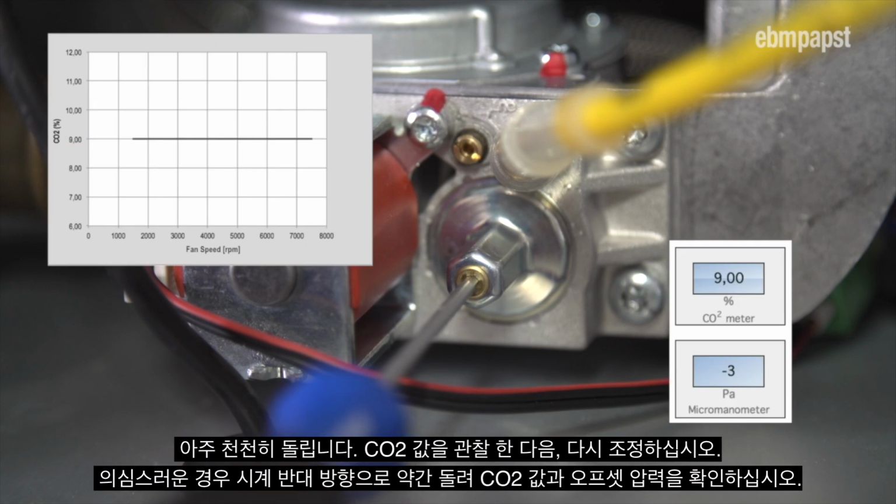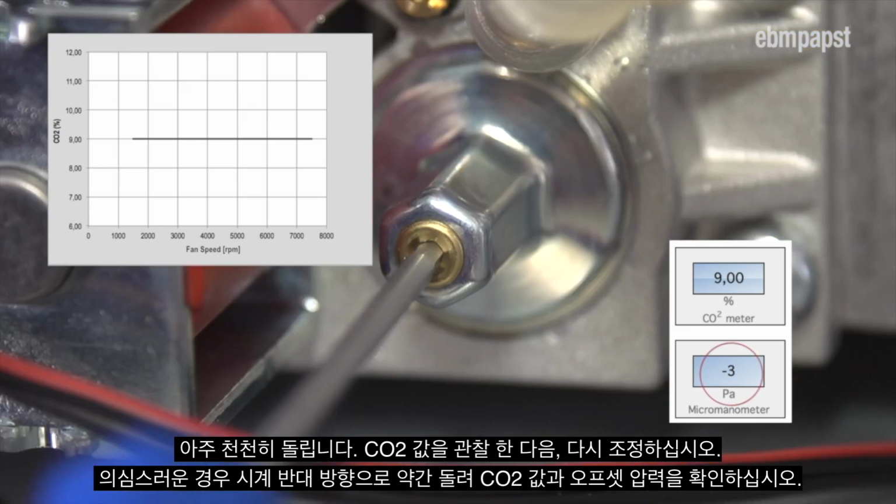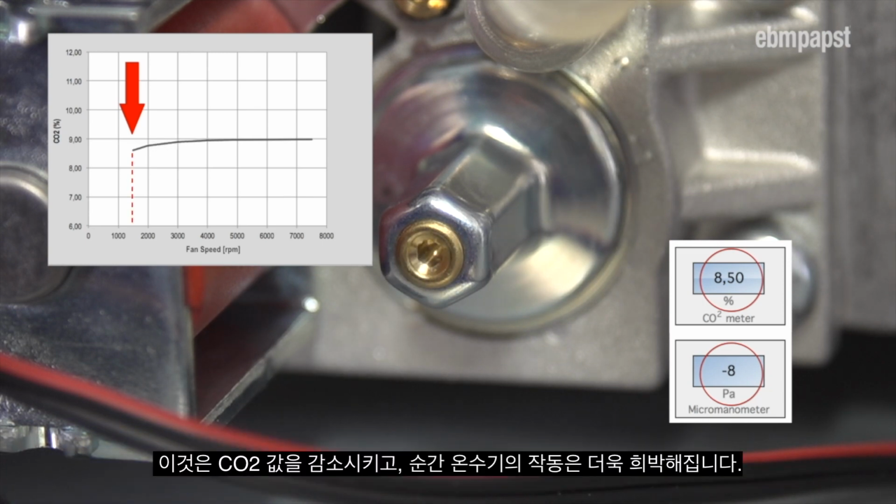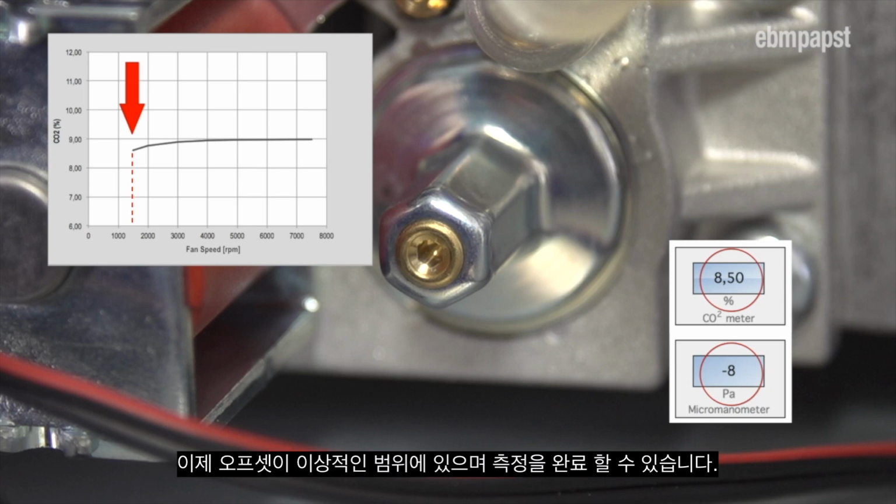Turn very slowly. Observe the CO2 value and then adjust again if in doubt. Turn slightly in counterclockwise direction and check the CO2 value and the offset pressure. This reduces the CO2 value and the operation of the instantaneous water heater becomes leaner. The offset is now in the ideal range and measurement can be concluded.